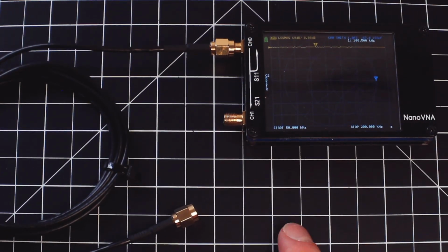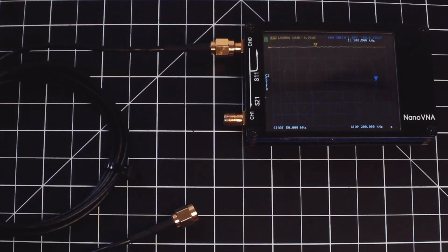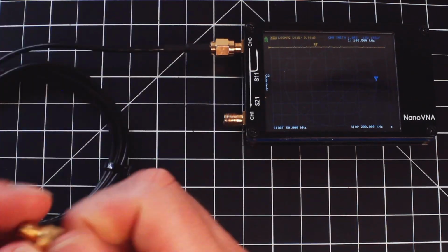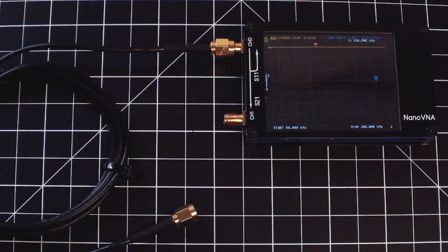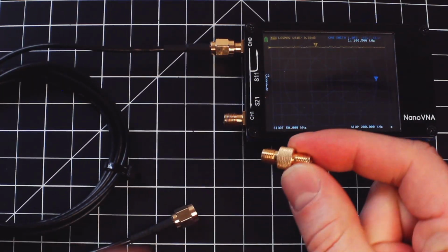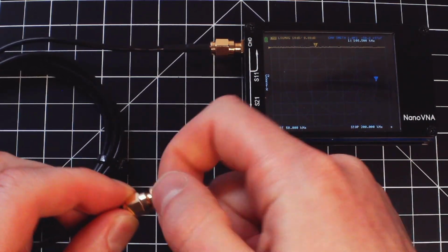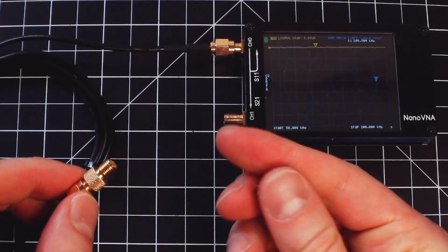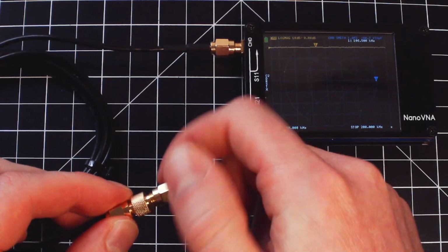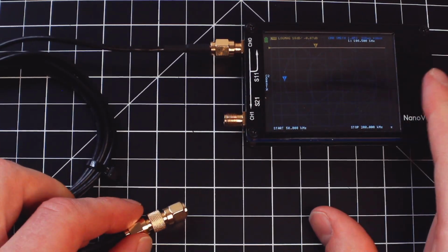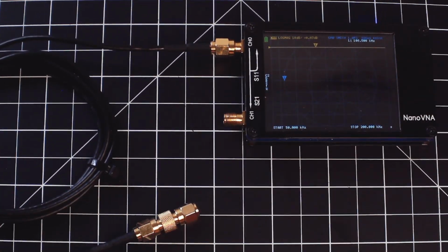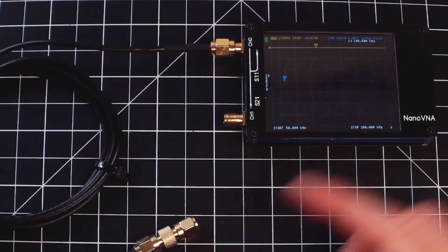Now, with that information in mind, you might be tempted to try the following measurement. I'm going to go ahead and grab a little barrel connector, like this guy here, and attach it to the load. And now I'm going to take my calibrated short circuit here and attach this to the end as well. And you can see how the Smith chart immediately jumped to the left to indicate the short circuit here.